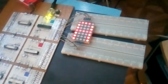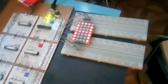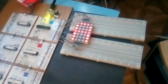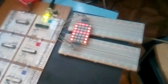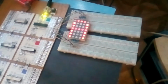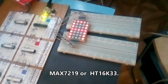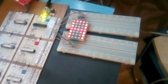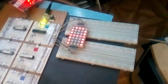speed right now that you are seeing is either maximum or very close to the maximum that this Arduino board or processor on the board can deliver. And a better solution to get a bit more speed is to use more dedicated ICs like MAX7219 and HT16K33, which some guys from the Arduino forums recommended to use.